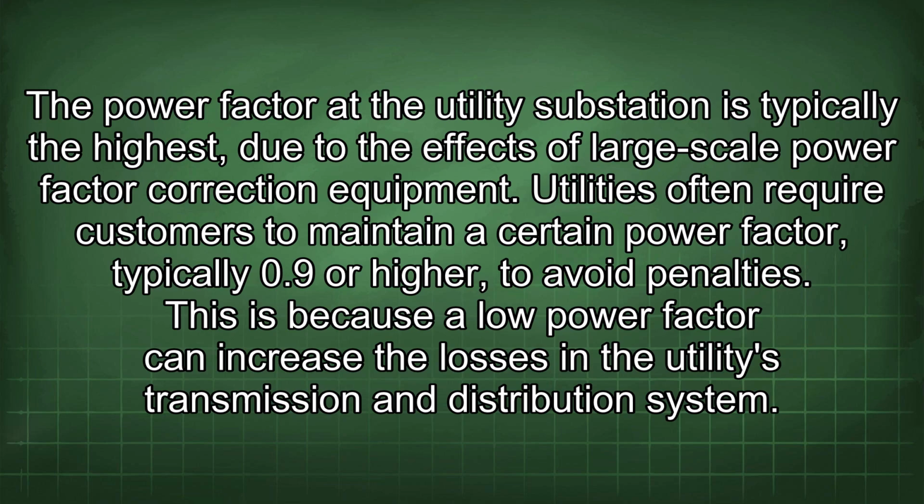Utilities often require customers to maintain a certain power factor, typically 0.9 or higher, to avoid penalties. This is because a low power factor can increase the losses in the utility's transmission and distribution system.